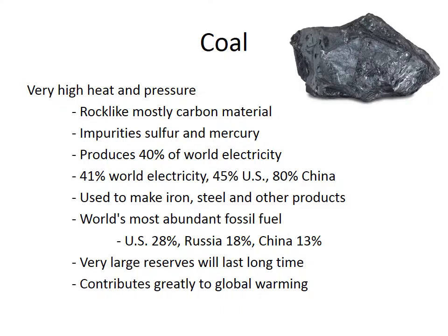Think of them as filters installed into smokestacks where this is burned. We usually use coal that contains less sulfur. And if we control the temperature at which things combust, we can change the ratios of the pollutants that we make. But reducing emissions even lower is difficult and it becomes expensive. You can change into what's called a fluidized bed combustion, which reduces the amount of carbon dioxide and sulfur oxides coming out of the system.